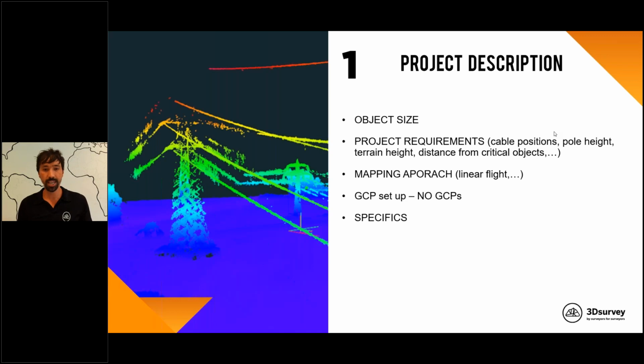So our suggestion is fly high enough. And the second option is the approach you need to take. We suggest you turn the camera gimbal a bit to the front. I did it with a 60-degree camera gimbal and got really good results out of it. This helps you increase the overlap between images, because if the camera is pointing in front, we get more area in the same image, longer cable size is on the image,